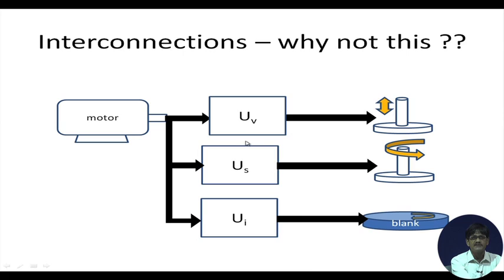So, let us check what possible problems it might be giving rise to. I change the gearbox setting of UV, I make it double. So, number of strokes get doubled. I find that the millimeters per minute has not changed. So, millimeters per minute divided by strokes per minute becomes half.